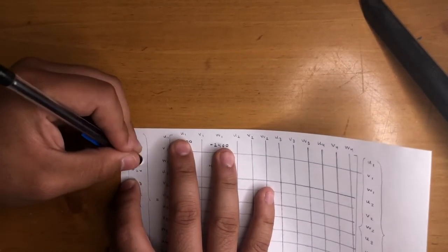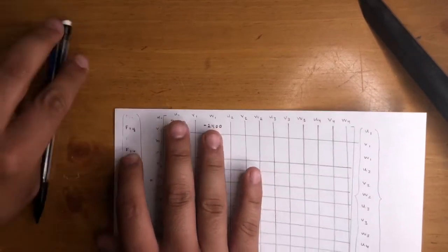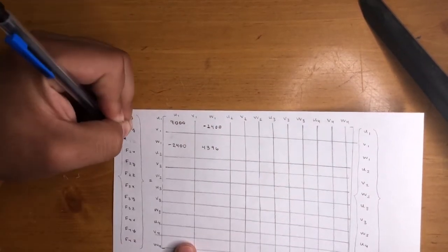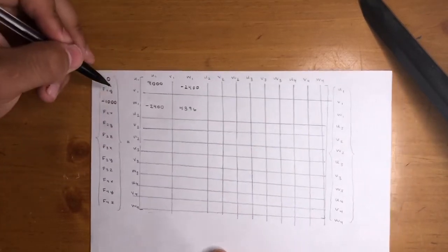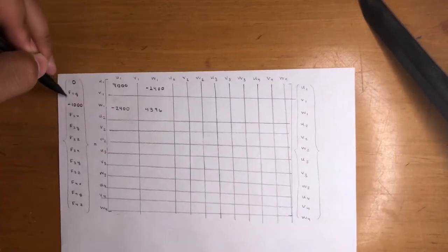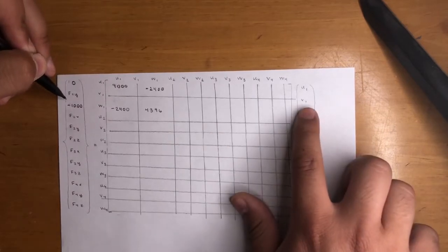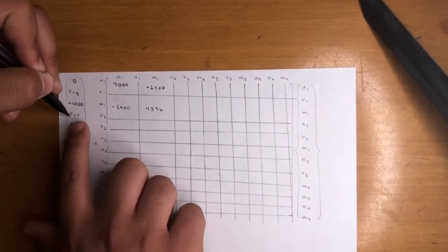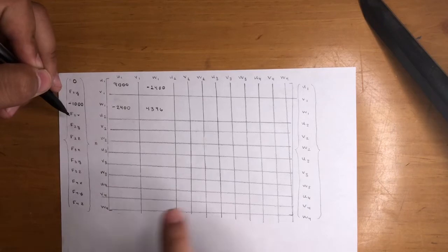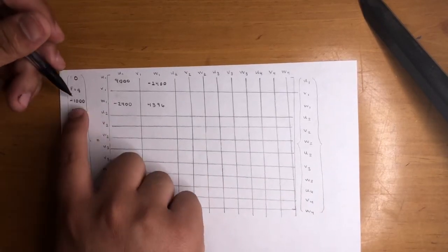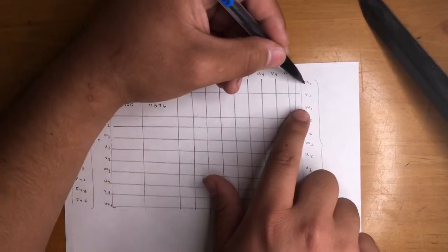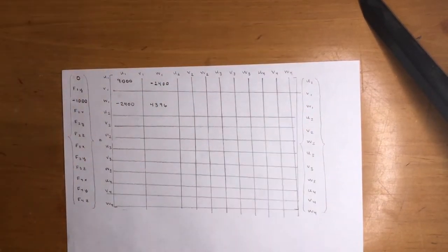And at z, it's negative 1,000. Okay, so it's 0, negative 1,000. And we know displacement at every other one. Displacement v1 is 0, and then remember we applied all these boundary conditions. All these were 0. So you knew displacements, you didn't know force. And here we know the two forces, but we don't know displacements, u1 and w1. And that's what we're looking for.